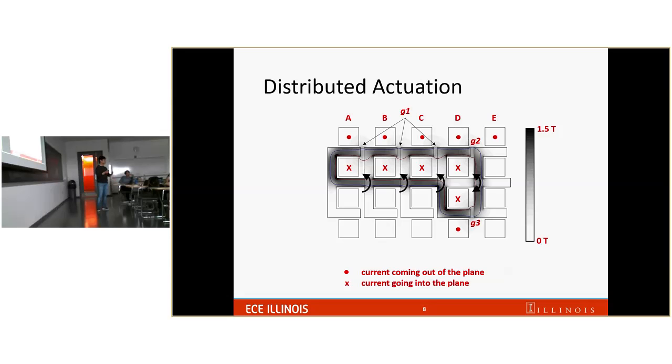Yeah, it can help smooth movement, but at the same time it'll disturb my movement, because I will need more current to make it move a lot. Does that make sense? Well, part of it though is you need current running all the time to keep it in a stable position, as opposed to no current in a neutral position. So there are trade-offs, right? Basically you've got to have it on all the time just to be in what would be a neutral position, not using any current.